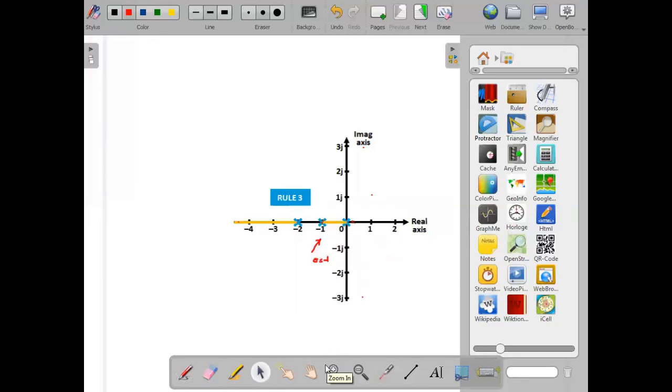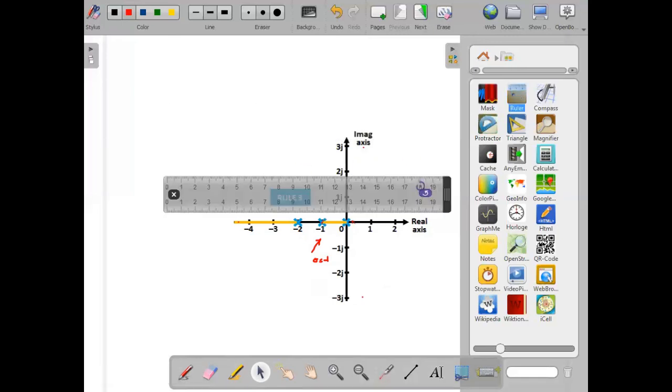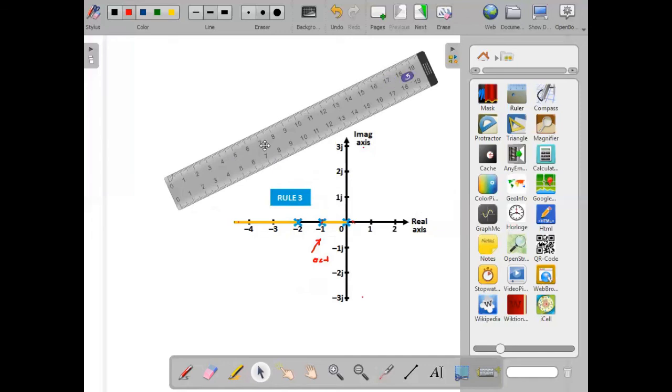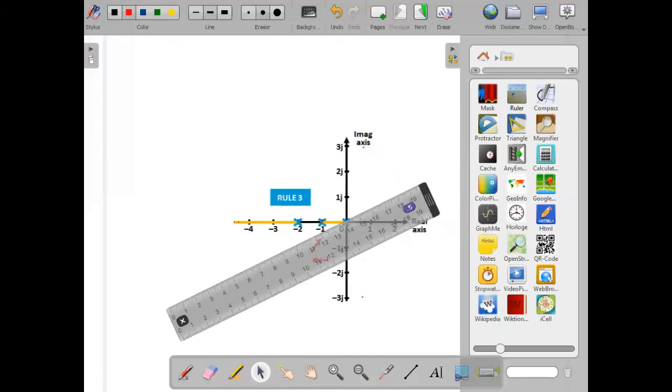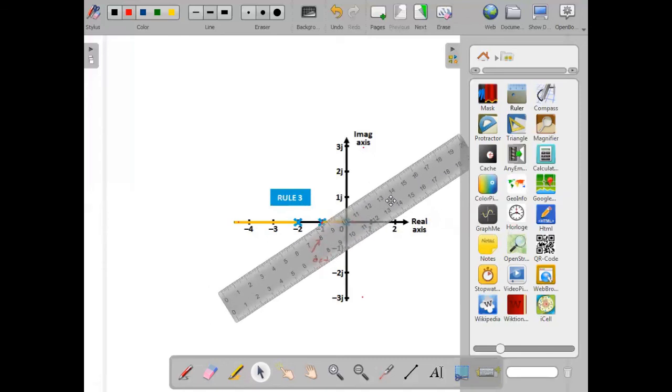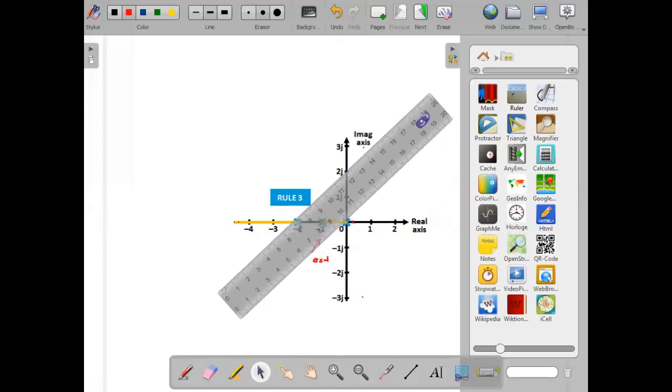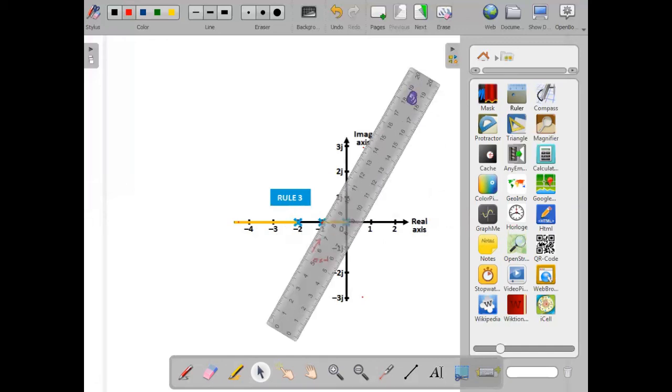Once after marking for theta 1, theta 2 and theta 3, let us draw the asymptotes. Let me take the scale and mark the asymptotes at an angle of 60°. The plot is here, 60° plot. We have already marked 60°, making use of the protractor. Now we are going to join the centroid and plot the angle of asymptotes.